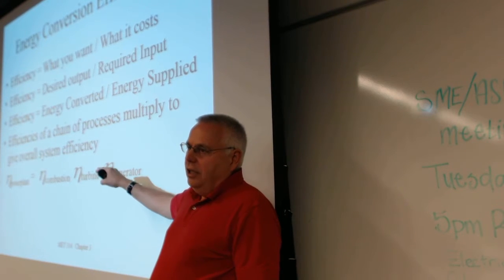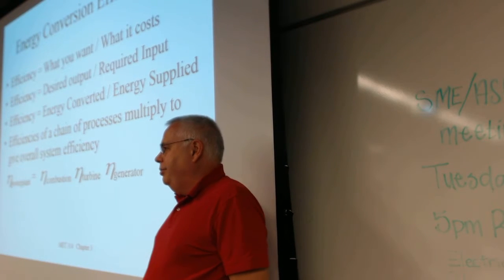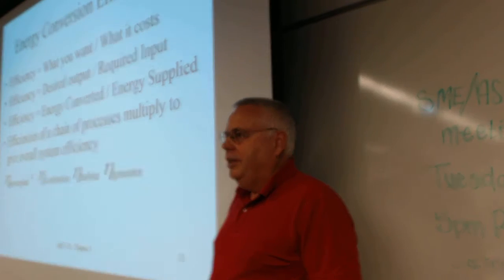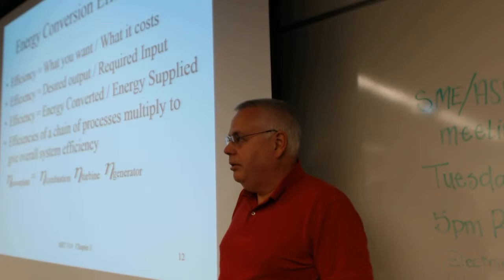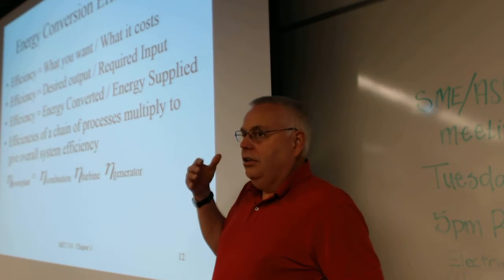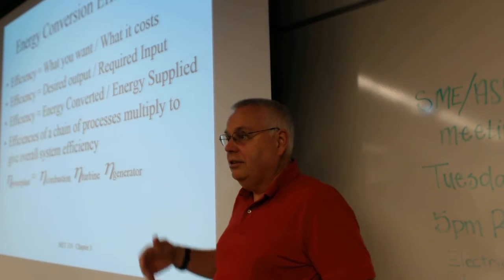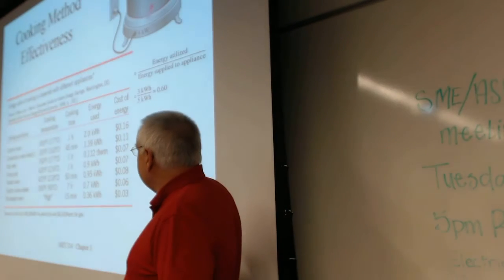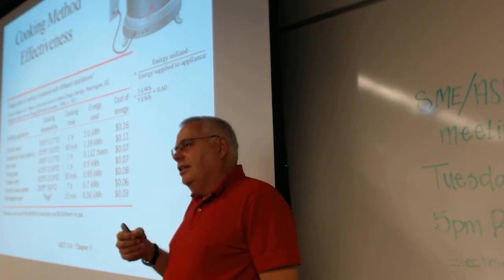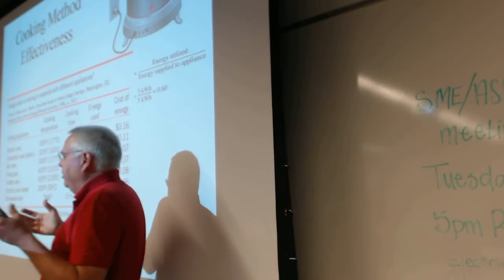Thermal efficiencies, like the very best power plants, maybe 42% efficient for a super huge one with a whole bunch of complications. That's like really, really good for the whole power plant. Which you think all the things going on, that's a whole chain of efficiencies, and altogether they get you to 42%. They all have to be like 85, 90% efficient processes to do that. Now there's the effectiveness, which isn't exactly the same as efficiency, because you're not comparing the same units necessarily.